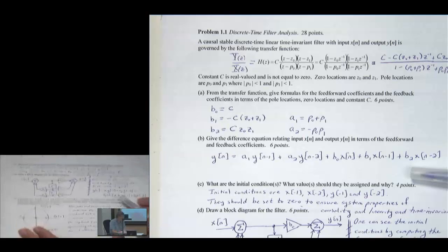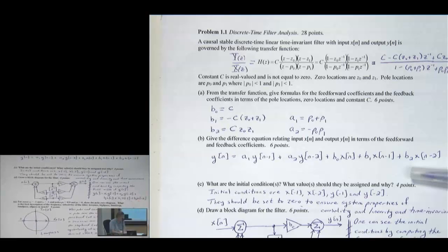Now in part E, we now know the selectivity, so we could, if you wanted to, in this problem, I didn't ask in part E, you could have set C to something. You could have set C so that the response at zero frequency is 1, for example, but it wasn't necessary for this problem. So two zeros and 2 poles, and I went ahead and added a trivial pole in there. I suppose I could have put the pole at 0.1 to see what you would do. It doesn't change much.